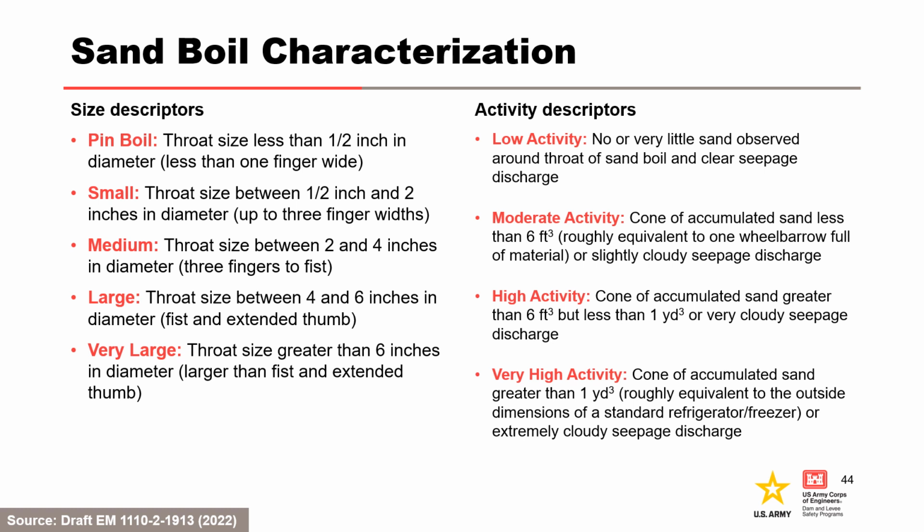Although intended for classification during flood fighting, this guidance can be utilized during a critical review of previous levee performance. For Mohawk Dam, all previous sand boil observations were reclassified using this guidance to help calibrate the team and overcome previous biases.